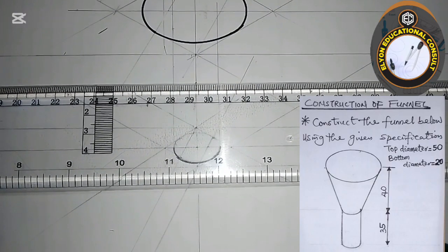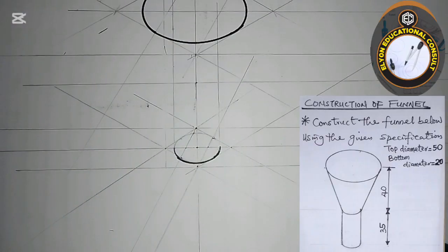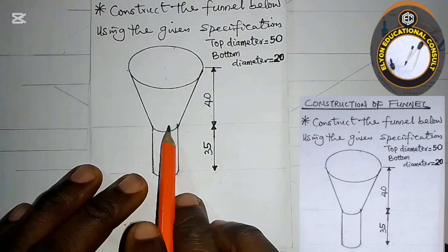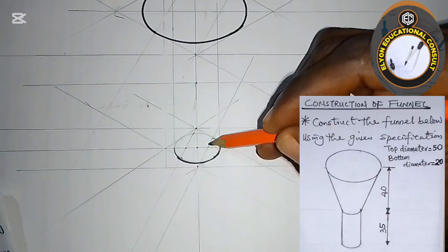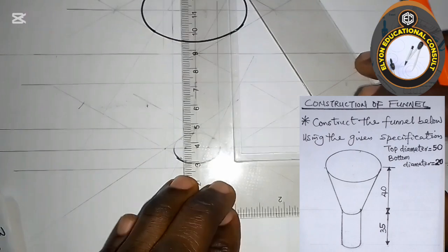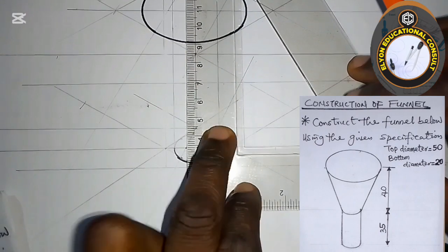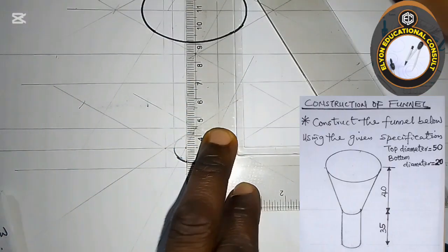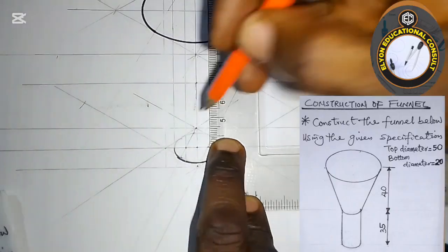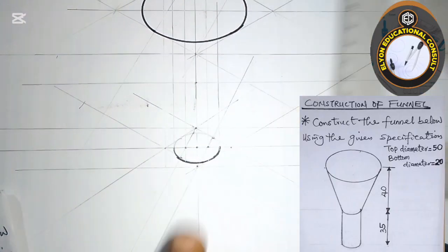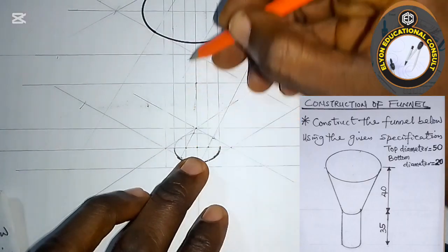I will draw this horizontal line, which is the center of that bridge we have there, on this side. I just want to transfer this. So I will take note of this point and these 2 points here, and project a line up from those points, then come to this other side and project another line up this way. I hope you can see that now. So we see these lines as we project them up.